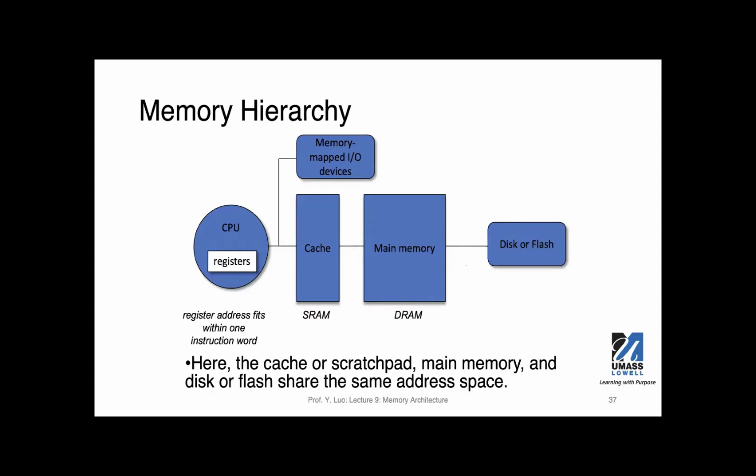All right, this is an example where we have cache in addition to the main memory. What we have here is a CPU that's going to do computation on data. The CPU will be doing computation on data that is stored in the registers, and the register file is on the same chip as the computing unit, part of the CPU. You can access this data very quickly. So the instructions will be able to access them, do the computation, and store the results back to them.